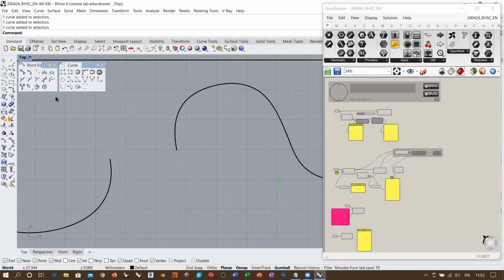So what I can do is take a control point curve, make it start from here, eventually, but it's not mandatory, eventually place the second control point aligned with the tangent to the first line, but it is not necessary. And I need first control point, second and third, and then I need 1, 2, and 3 control points.